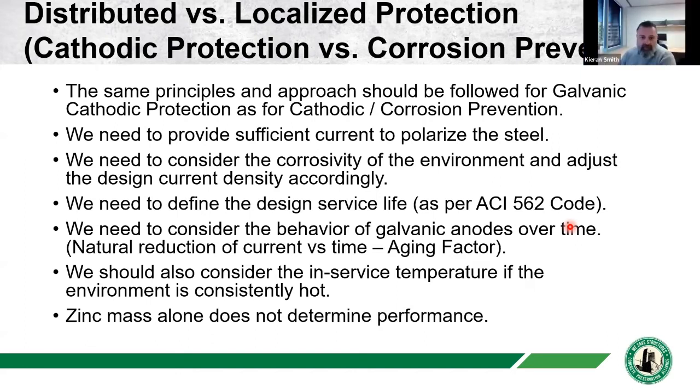Oops, we have another one. Do you expect a distributed galvanic system to meet depolarization standards, such as 100 millivolts after 24 hours? And what are the limitations, such as concrete resistivity? And do you happen to have any data around the uniformity of polarization given the large spacings you are specifying?